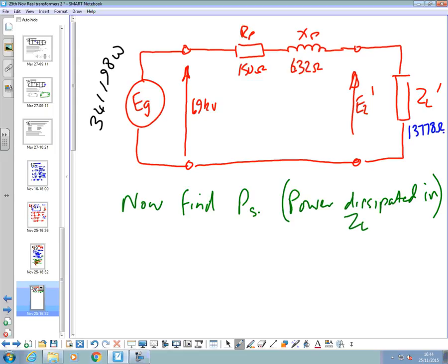You can't reflect that power because that power there is not what's here. You're going to get into trouble if you start reflecting powers. But what you can do is find this voltage and reflect it over the other side. Find the primary current reflected over the other side. Multiply them two together to get S on the secondary side, and then extract the secondary power from that.